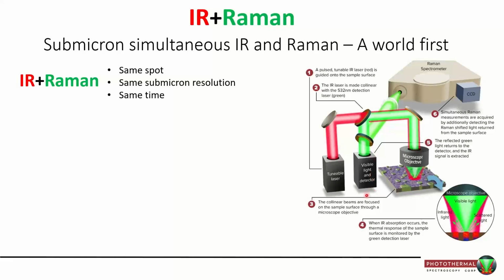So that visible detector extracts out the modulated infrared components in there, but because we are using a Raman grade green laser, you've got Raman scattering happening all the time. Whether we like it or not, whether we even use those Raman scattered photons or not, they are there. So we take advantage of the fact that there are wavelength shifted Raman photons.